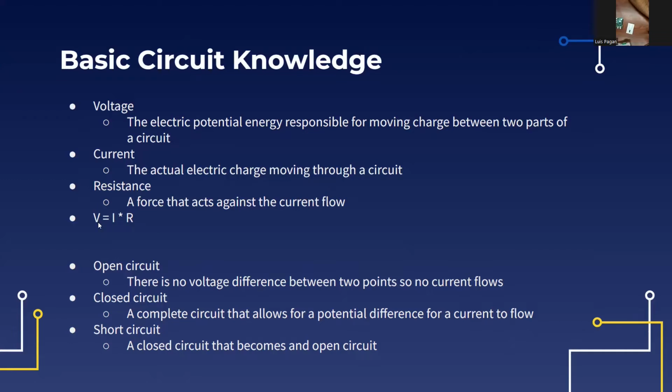In this case, we're going to be using a resistor for an LED, because normally the resistance is negligible, meaning the voltage is set, let's say, to 5 volts. In order for this equation to remain true, if R is very, very small, then I, the current going through that device, in this case the LED, would have to be very, very large. And the LED is not capable of handling that kind of current. So we want to add the resistor to bring the current down. But that's for a little later.